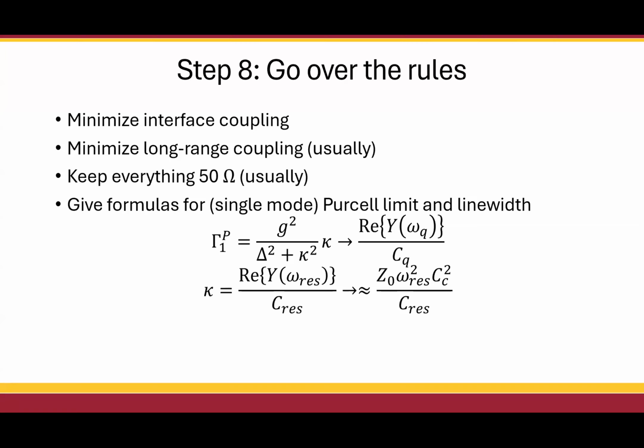Maintaining a constant impedance. And this one, I do actually like to go in just a little bit more on the why and the how. The why is basically to minimize reflections. You can just show them the formula for reflection. The how, basically just maintain a consistent size.